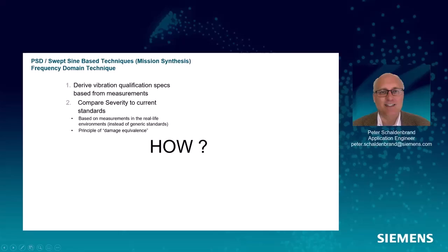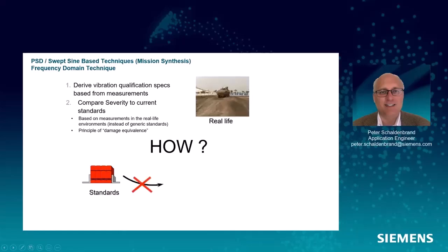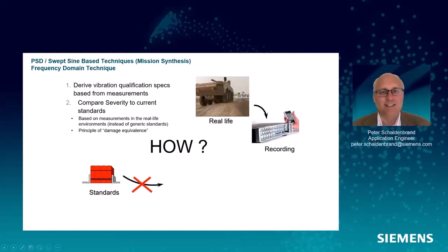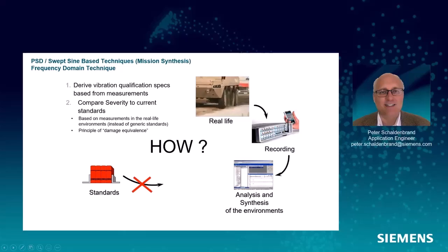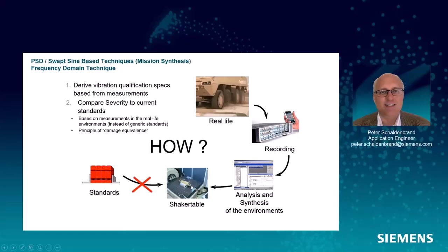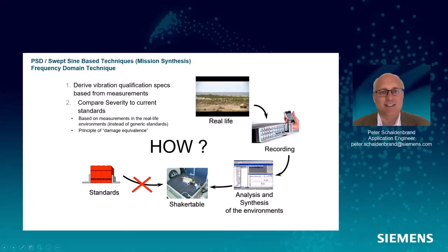A lot of times people use standards, so maybe we've taken some field measurements and we want to see how the field measurements compare to the standards. So how are we going to do that? Well, we could just use a standard, but we're not going to do that. We're going to take some data, measure some input accelerations, we're going to calculate some functions, and we're going to synthesize a profile on electrodynamic shaker test. And that's what we're going to go through in detail.